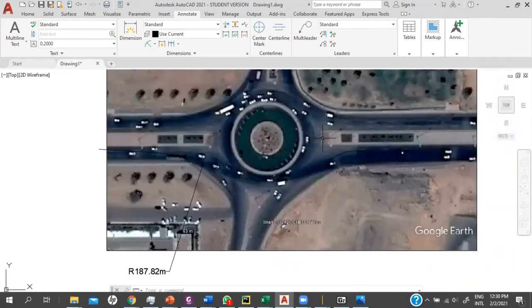And of course, you can say that there is no deflection in the splitter island here. And also, this splitter island does not prevent vehicles from making wrong way maneuvers, and so on. There is no pedestrian crossing. There is no entry line. Then you can check also for the heavy vehicle. I don't think the heavy vehicles will be a problem here because the diameter already is large.